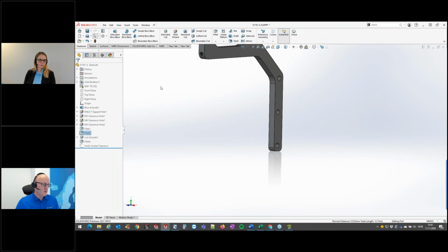What you might do a couple of times is to use a different way to rebuild, which is Control Q. And Control Q does exactly the same thing, but it rebuilds from the start of the tree and all the way through. So it rebuilds everything in the file.